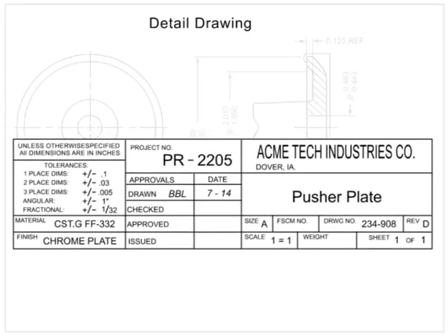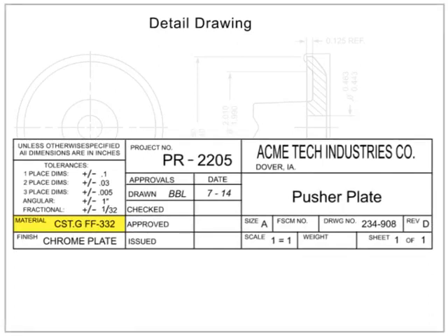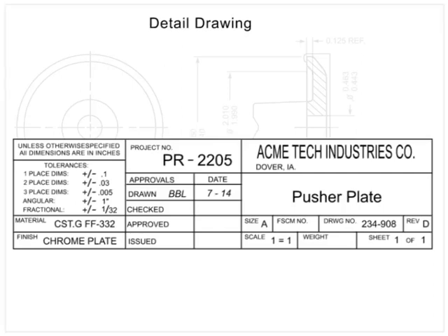In this drawing, the casting from the last example was used as the starting material. This machining drawing will remove material from the original casting and add the finishes required to produce a final product with its own unique part number. Only the dimensions necessary to convert the original cast part into the new part are required. The casting dimensions are not shown.